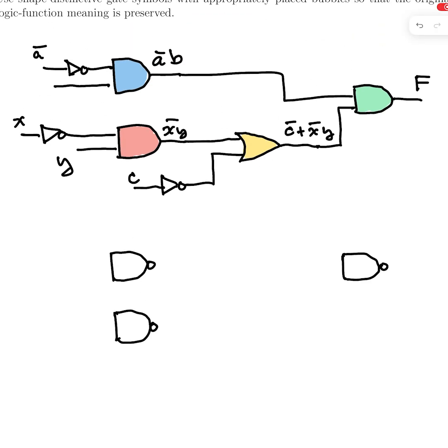I think of it as I want the AND function, but I want to implement it with a NAND gate. How do I take that function? I take the AND distinctive shape, put a bubble at the end, and I get a NAND gate. Similarly for OR. We talked about how, if you take an AND shape and push this bubble back through, it turns the shape into OR and puts the bubbles on the input side.